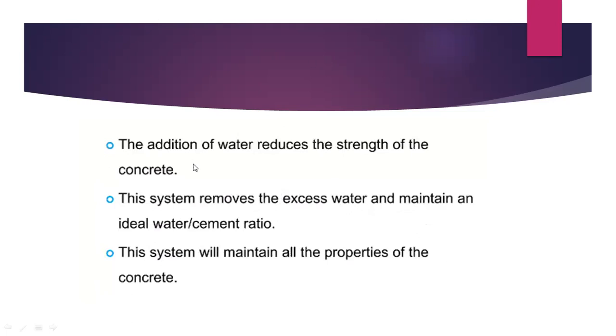But if we add excess water to increase both workability and the heat of hydration process, it results in a reduction in strength. That is the very first point given. To maintain optimum water content, this system helps in removing the excess water.